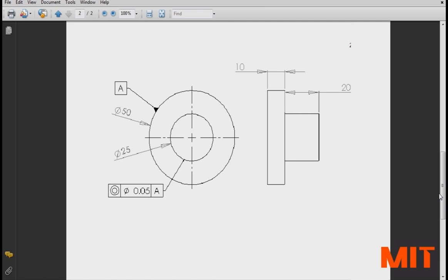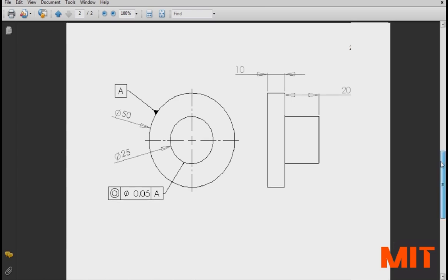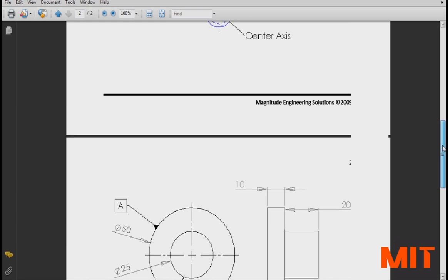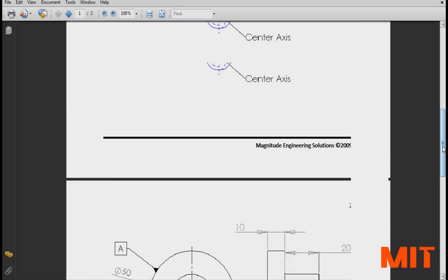I'll just show you quickly down below. So we're going to have kind of like two extrudes. We'll have a first extrude, which is our outer diameter, and then a second extrude, which is the smaller diameter, and we're going to apply our concentricity onto its location. So what we're trying to do is we have our original shaft, and we want the second shaft that's smaller that we're extruding to be positioned in the center of it to our specified tolerance.